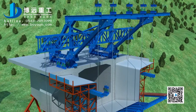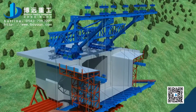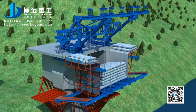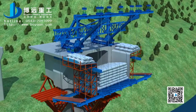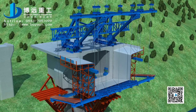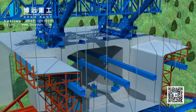Review the drawings and adjust various parts of the forming traveler again to the designed place. Pre-press the hanging basket structure according to the pre-press scheme. Compare the pre-press monitoring data with the Midas modeling stress data and remain consistent. Adjust the bottom elevation of the forming traveller. Install and fix the internal nose girder.